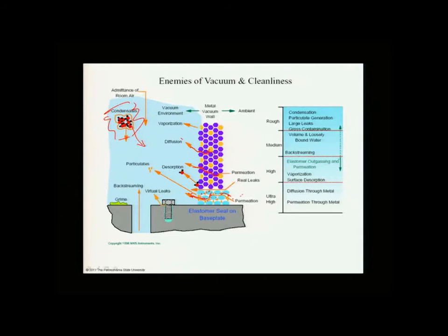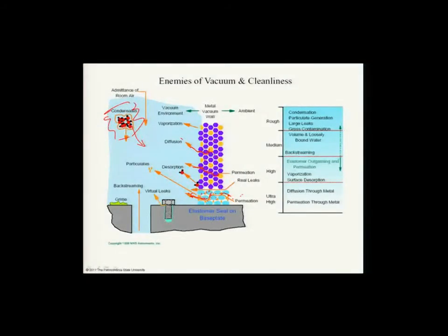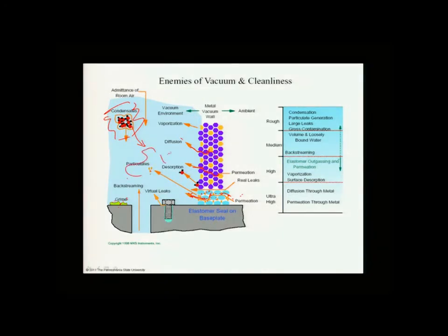And there can be all sorts of things, some kind of dirt in the vacuum system which can volatilize. It could be some kind of crud here because we weren't careful. There can be particulates from the previous processing that are producing particles that are going into the vacuum and moving around. Particles can be coming off of here. We can also have a virtual leak caused by something as simple as the threads on a screw.